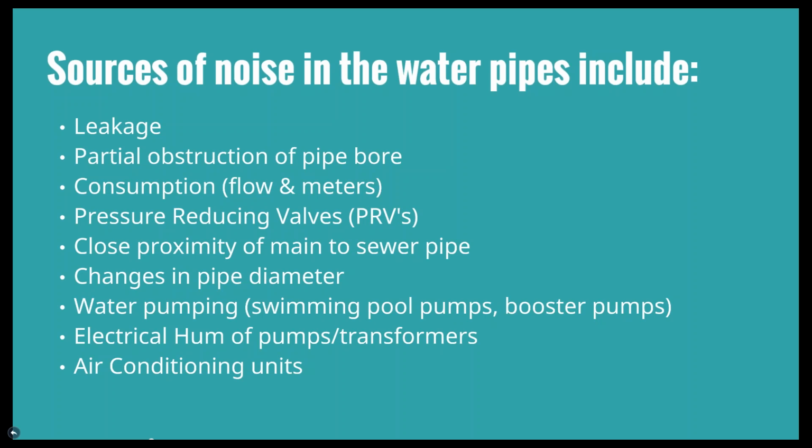When you are collecting data, you need to be aware of pumps in the area that can create vibration and noise through the pipe, and any outside noise can be a source. The more you collect, the more surveys you do, whether it's your own staff or your contractor, the more you can eliminate these things. But knowing that these things are out there is a critical piece of a leak detection program.